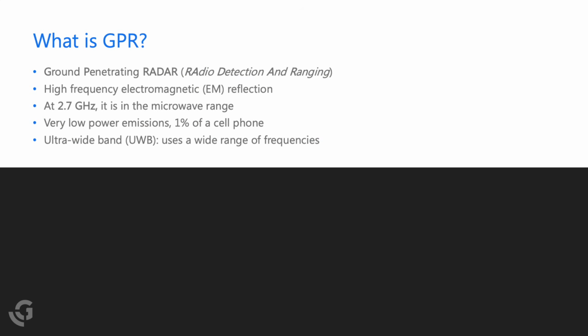Ground-penetrating radar, commonly referred to as GPR, uses radar pulses to image the subsurface. This non-destructive method uses electromagnetic waves to detect the reflected signals from subsurface structures. With GPR, we are transmitting and receiving high-frequency electromagnetic waves. We transmit a wave into the concrete, soil, or subsurface, and it reflects off different materials it interacts with. Once the information is received, we will know a little bit more about what we just traveled through and what type of materials might exist below.